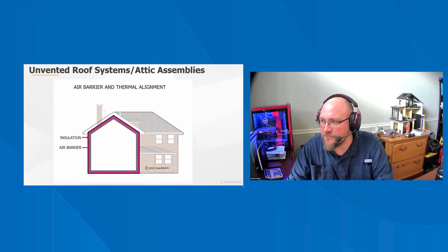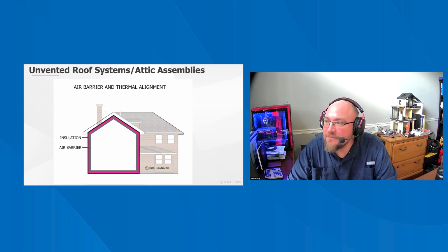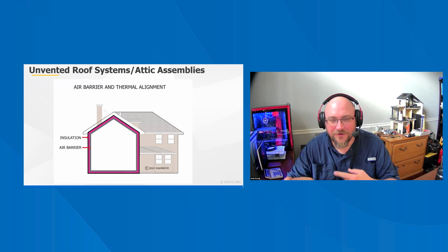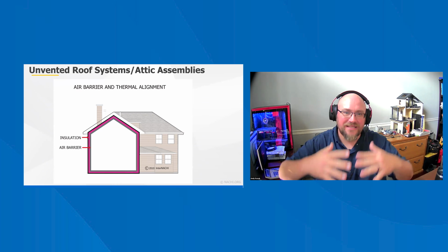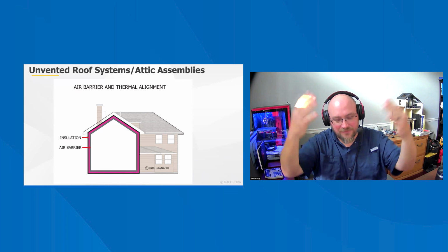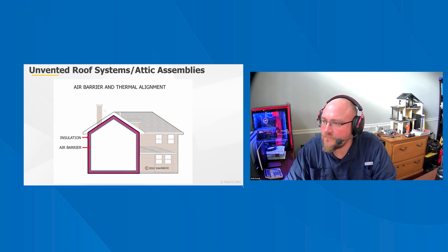So for unvented roof systems, the condensing plane is the underside of the air impermeable foam. When they're properly installed, condensation should not exist because the temperature of the interior face of the foam should be about the same as the interior air temperature. But when you don't have that rotation of air, that moisture-laden air gets up into that space that does not rotate the air out, comes into that condensing plane, and then drips down.